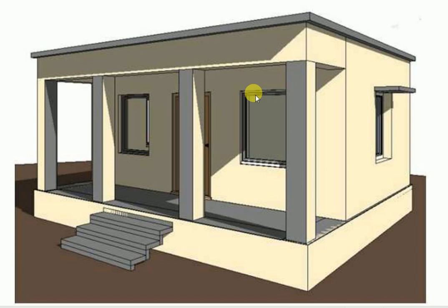Nowadays, RCC, reinforced cement concrete lintel, is provided in buildings. Its size depends on the opening size. Depth and width of the lintel is generally 150 mm and 300 mm respectively.